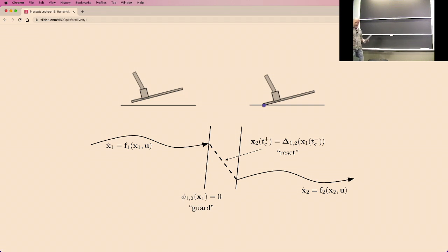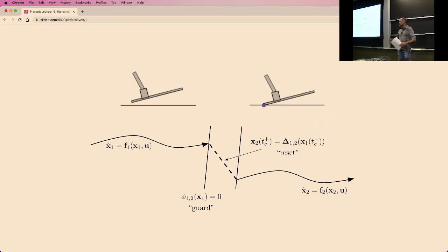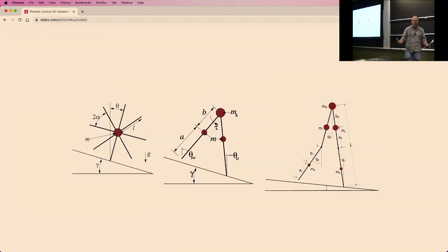We've given you trajectory optimization and now stabilization and even Lyapunov analysis, shown how to do them for trajectories and for limit cycles. And I've given you a series of models, from the rimless wheel to the compass gait to the kneed compass gait, implying a natural progression as you add more and more links. We have the basic machinery for how to do that.